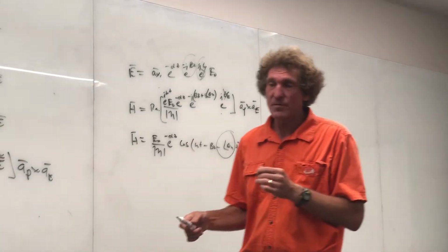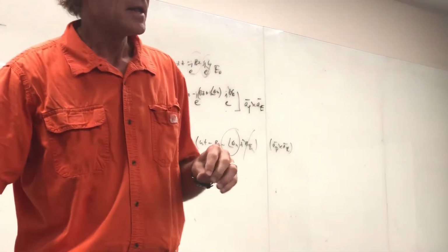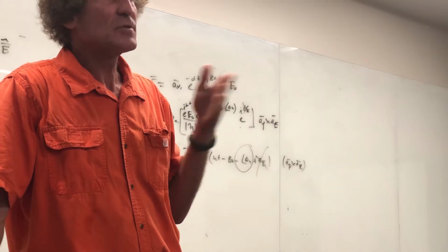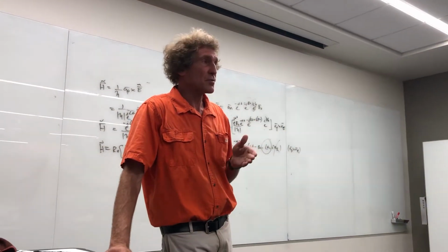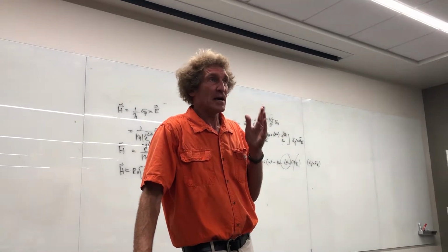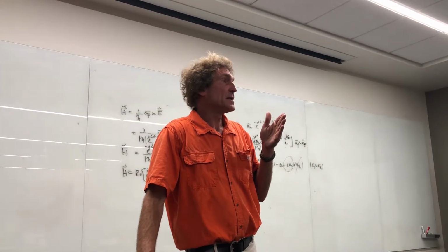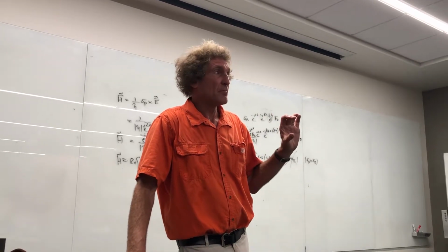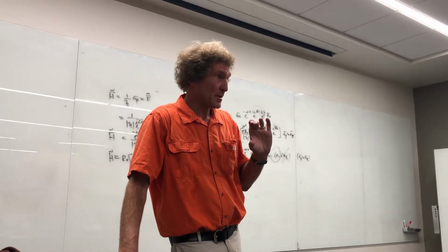I don't know if Dave Irwin taught you this in circuits or whoever you had, but there used to be a saying, Eli the Iceman. E was the symbol, and it still is in Britain, for the voltage. I is current. Well, Eli: E in an inductor, or voltage in an inductor, is always leading the current by 90 degrees. I don't know if you remember that.